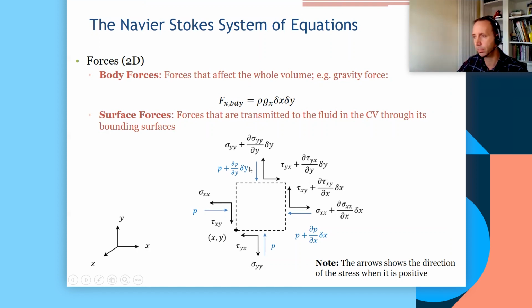If you have differences in velocity at the interface, it means you will end up generating a shear stress. If you've got compression because you've got more fluid going to the right on the right-hand side of the interface or boundary instead of the left-hand side, then you can get a compressive stress there that translates into compressive force.